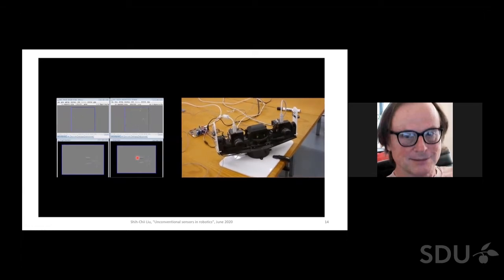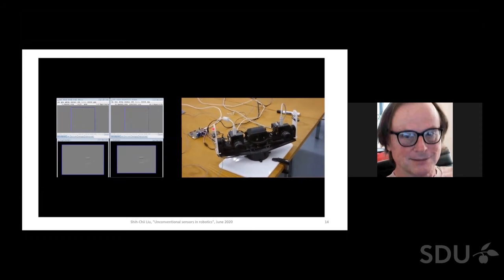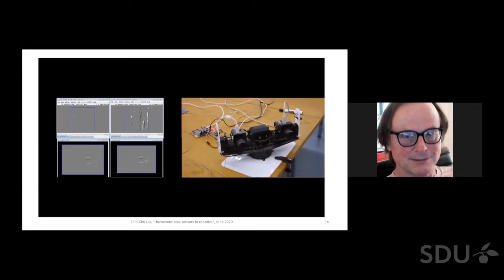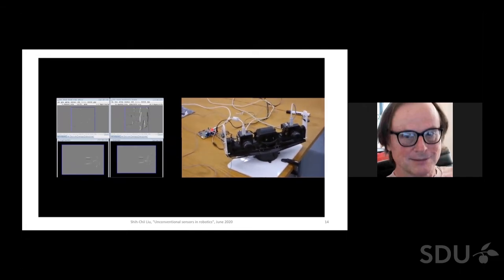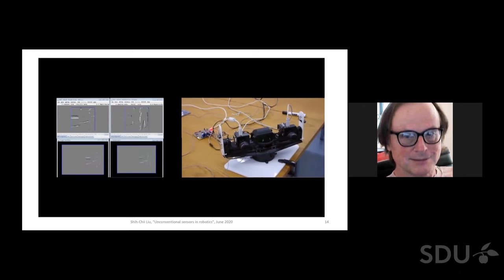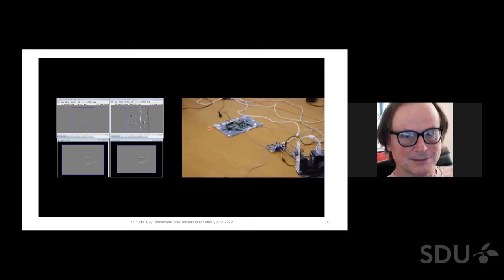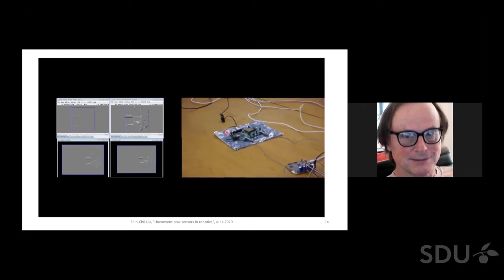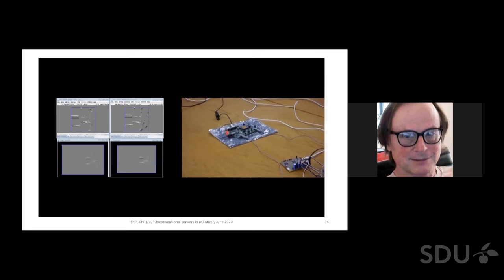Here you can see the robot head with the 2 DVS cameras and the 2 microphones on its sides. The jittering motion of the cameras is clearly visible. Each of the cameras is connected with a USB connector to the PC. The 2 microphones are hooked up to the Cochlea AMS1B board.